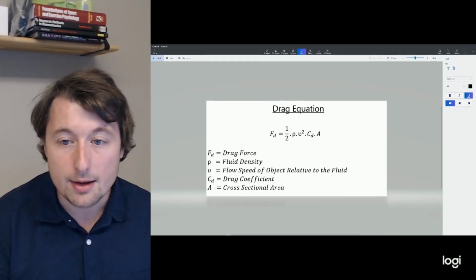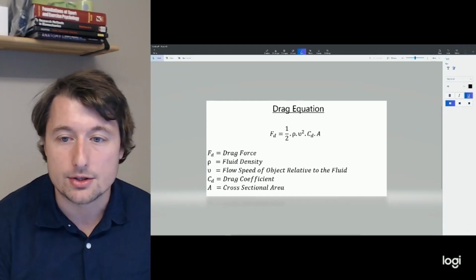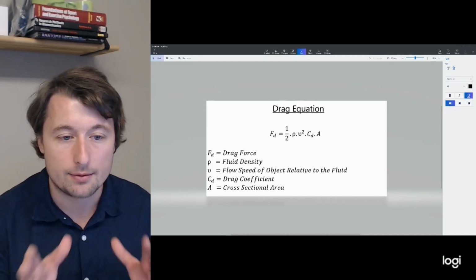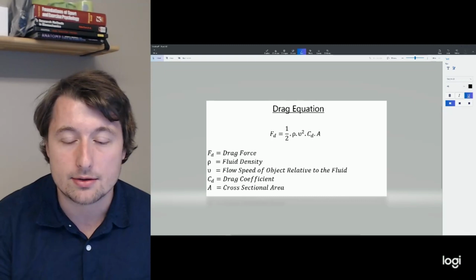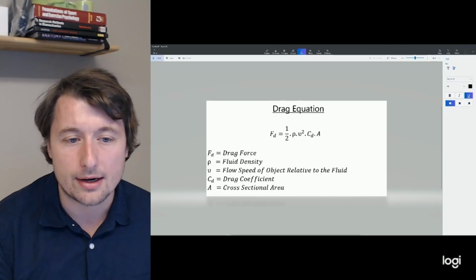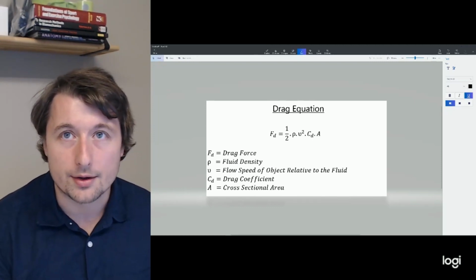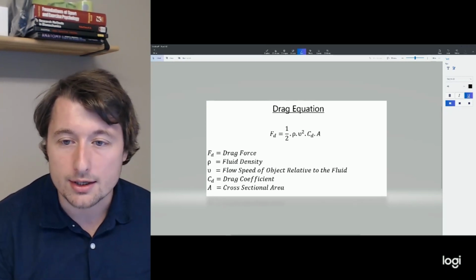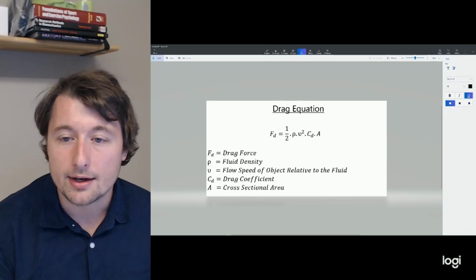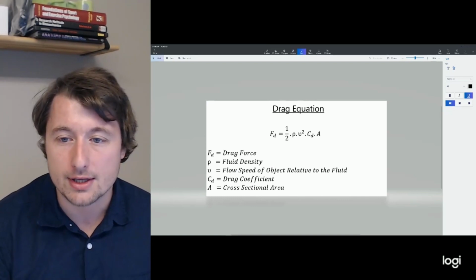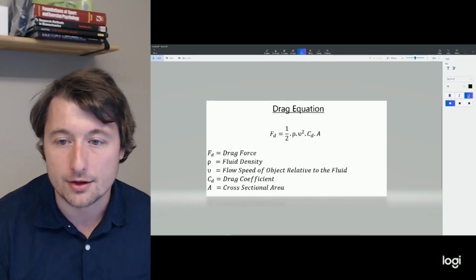So the A part we'll talk about first just because it's a little bit easier. So A is basically just the frontal area of your position on a bike. So if you looked at you from head-on position, how much that area is hitting the air. That does vary a little bit when we're starting to think about side winds, for example, because then the movement of the wind isn't entirely parallel to your movement. So it's something that can be a little bit oversimplified, thinking only about it as a frontal area, but generally that's the direction of your travel. So that's what we're interested in.